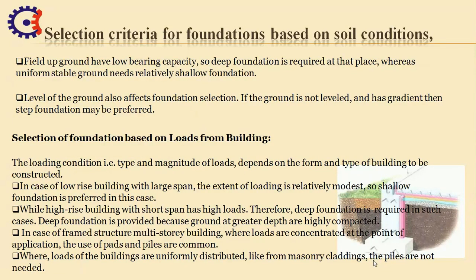In that case we are going for strip foundation, pad foundation, raft foundation. In case 2, where trees, hedges and shrubs are close to the foundation location, or there is a plan to plant these trees near the structure in the future, in that case we are going for concrete piles supporting reinforced concrete ground beams and precast concrete floors.